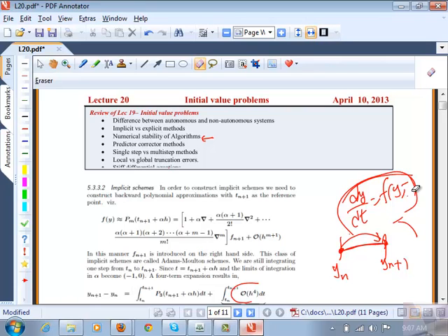Because there is also the potential for it to have a periodic state, through a Hopf bifurcation point, or a chaotic state. So essentially, a system that evolves in time can reach a steady state, or can have sustained oscillations or chaotic response. Now, for such a system, when I have dy/dt equal to 0, if there is a steady state, I get the steady state solution by solving that. And that means when I'm plotting the function y versus t, I might get something like this, and then it reaches a steady state.